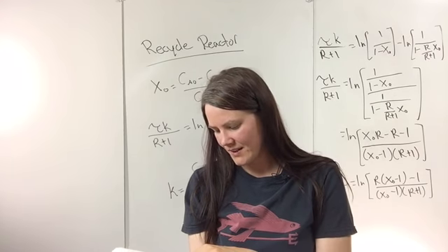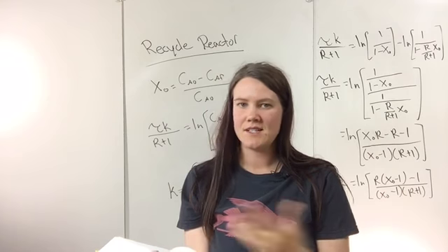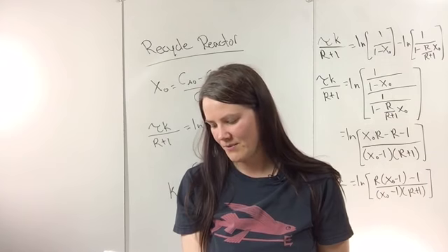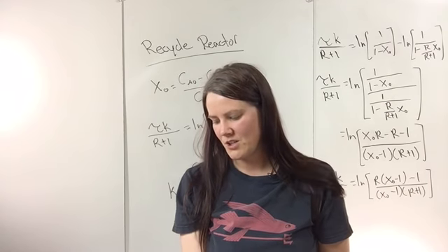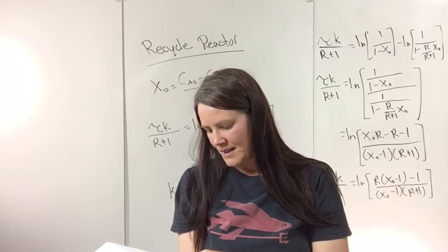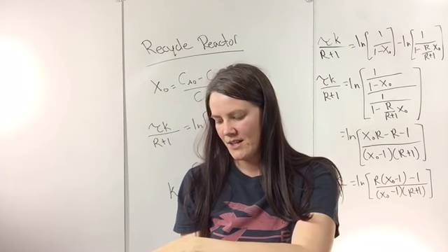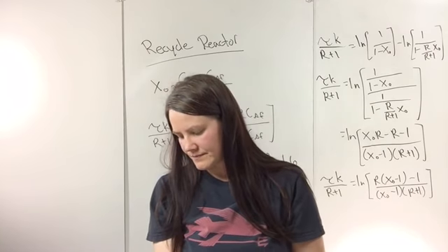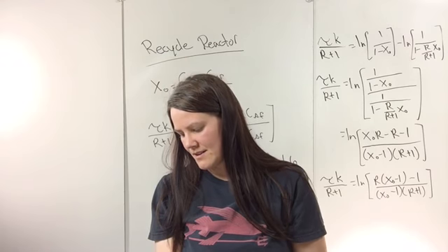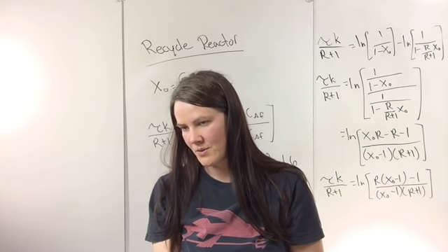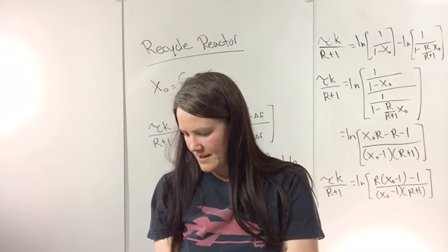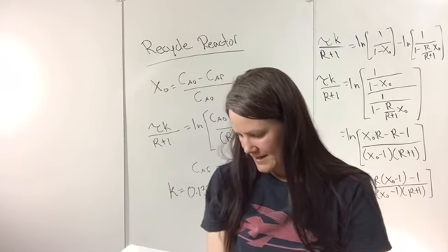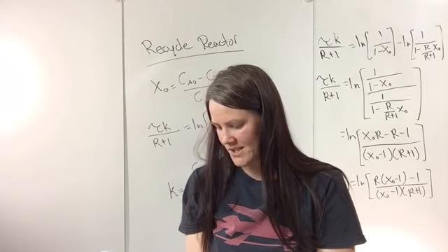So you would need to calculate dCA/dt, because you'll probably have concentration and time. There were 3 different ways you could do that: the graphical method, the finite differential method, or the polynomial method. Then you plot the natural log of dCA/dt versus the natural log of Ca, and then you can find the reaction order, which is the slope, and you could find K from the y-intercept.